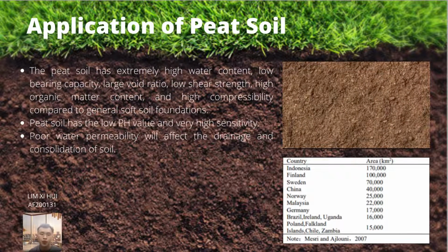The application of peat soils. Peat soil actually has high water content, low bearing capacity, large void ratio, low shear strength, high organic matter content, and high compressibility compared to general subsoil foundation. It also has a low pH value and very high sensitivity.